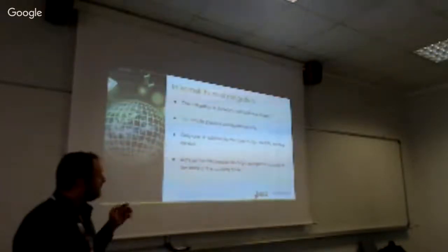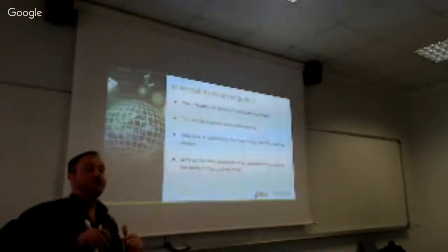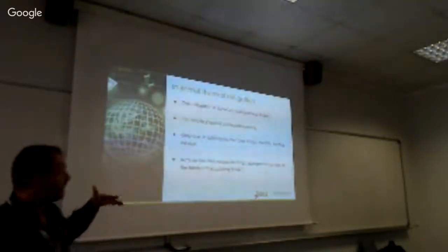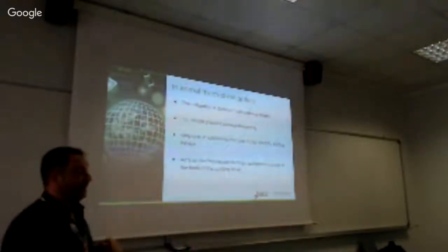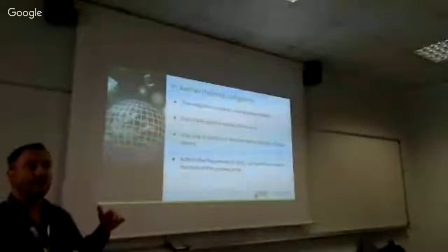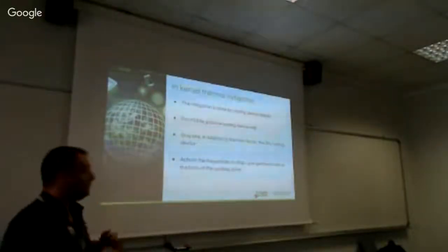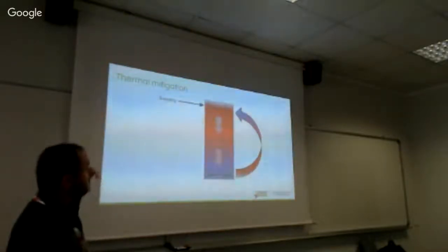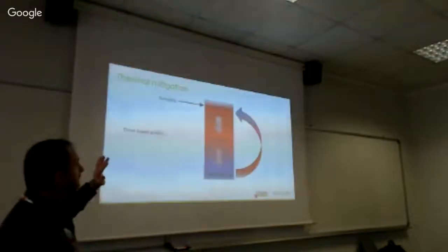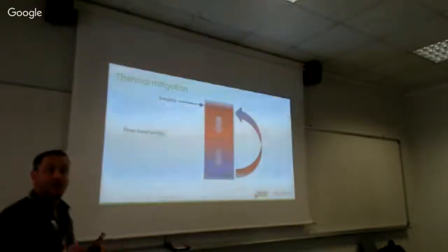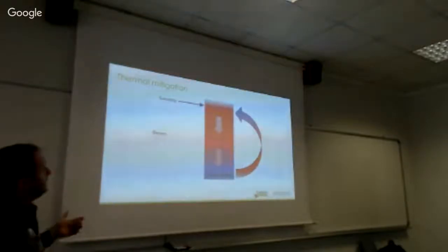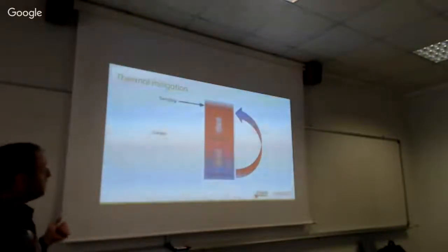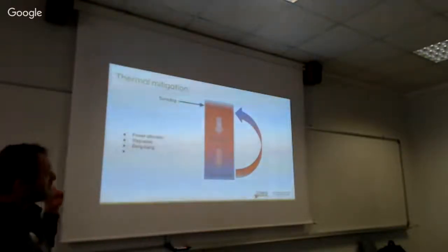So the idea with the CPU cooling device is when the temperature is increasing, and we reach a specific threshold we define in the device tree, we reduce the frequency. And then as soon as the temperature is decreasing, dropping, then we increase the frequency again. For that, we have the sampling. The sampling is getting the temperature based on a polling. You find the polling in the DT. The sensor is on the SoC, giving the temperature back. Then that's transmitted to the governor.